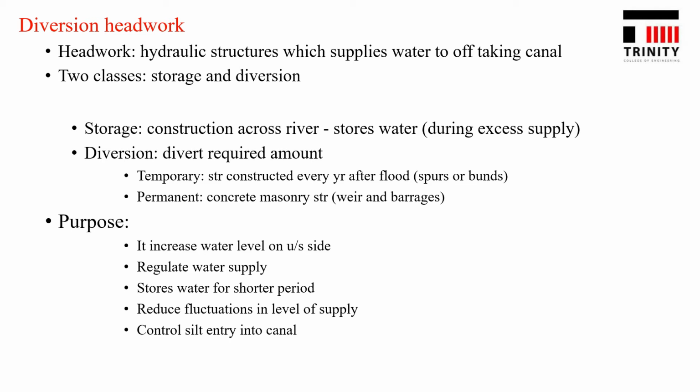Now, what is the purpose of headworks? Actually, it increases the water level on the upstream side. That is, on a river channel, we put a barrier across, and normally on the upstream side, water level increases. Next, to regulate the supply of water. Next, to store water for a shorter period. Next, to reduce the fluctuations in the level of supply.